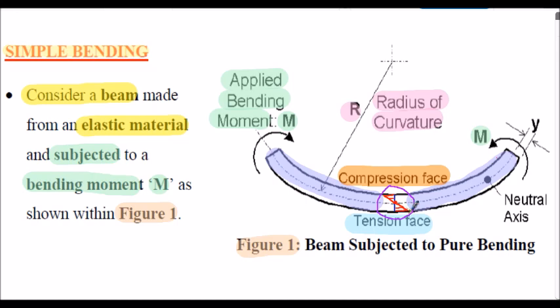At the bottom of the beam, maximum stress is in tension, and the top of the beam in this particular scenario, the maximum stress is compressive. The distance shown as y here is from the centre line of our section to the outside surface. The neutral axis is the location where there is no strain in the member, so there's no bending stress occurring at the neutral axis.